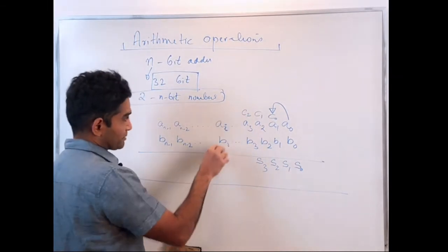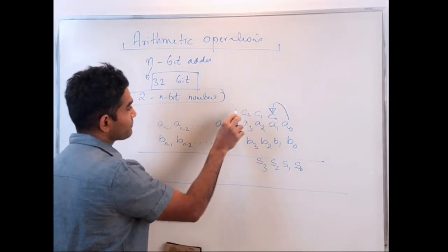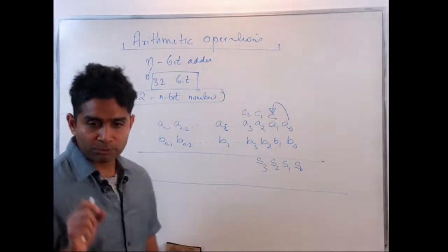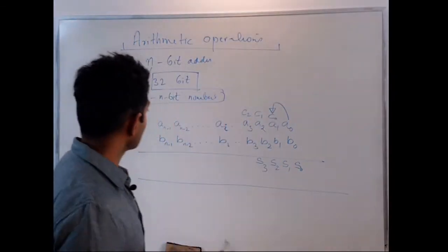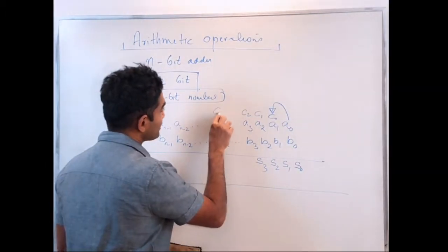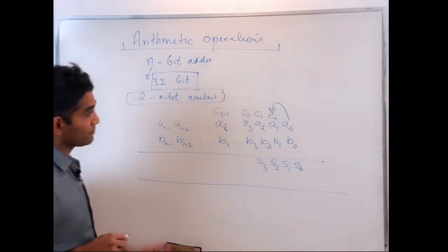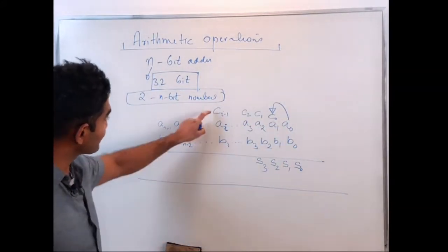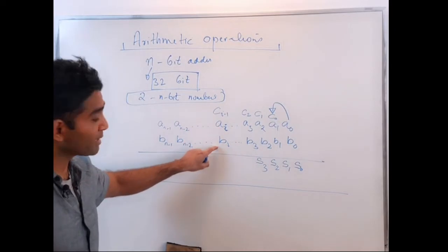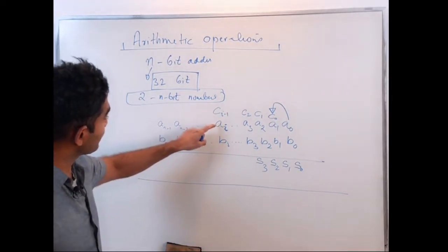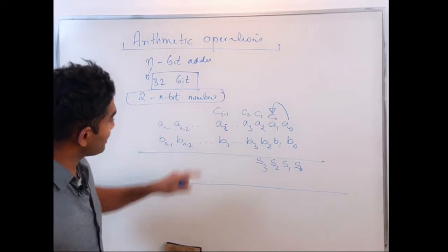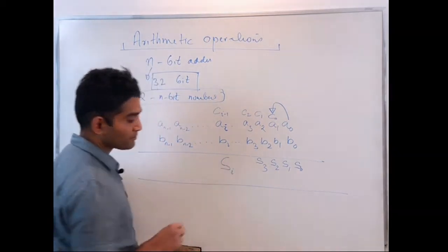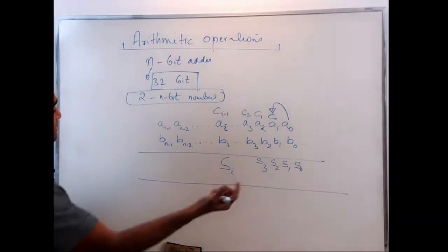At some intermediate bit position, basically what I'm doing is exactly the same operation. At every single bit position, I'm doing the exact same operation. Right? I'm taking Ci minus 1, that's the carry out from the (i minus 1)th position. I'm adding that to the ith position. I have Ai plus Bi plus Ci minus 1. I get some Si and some carry out that gets propagated.